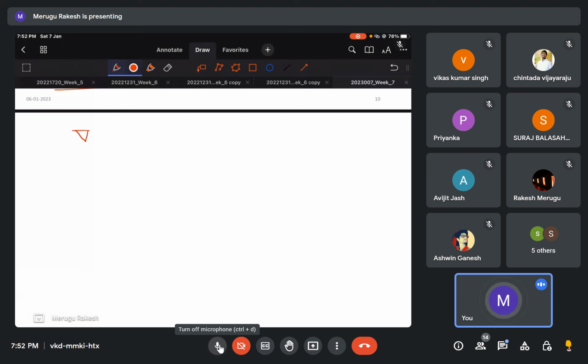This is one of the inverted triangles. This corresponds to values given in terms of CLA. The surface roughness or surface finish should be in the range of 8 to 25 microns. Suppose I have two inverted triangles, the surface roughness is limited to 1.6 to 8.